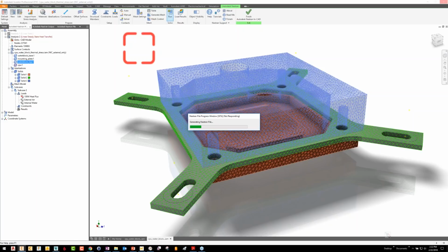If possible, and you plan on transferring these thermal results to a structural, it's good to have a finer mesh on your heat transfer problem than on the one that you're transferring it to. It just tends to work better that way. The meshes are going to be different, most likely, because like I said, there's different considerations in those two types of problems. But if your thermal problem is a finer mesh than your structural, you should be in good shape. When you go the other way, you tend to see some weird behavior.